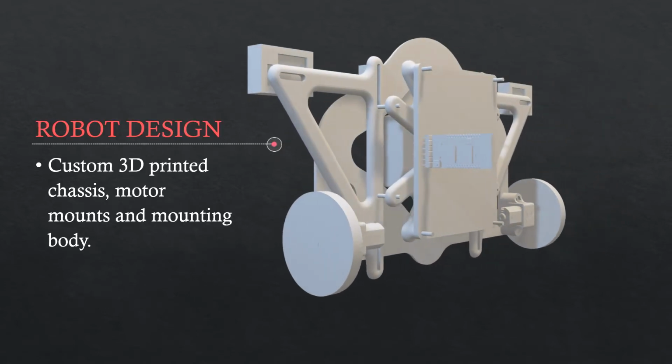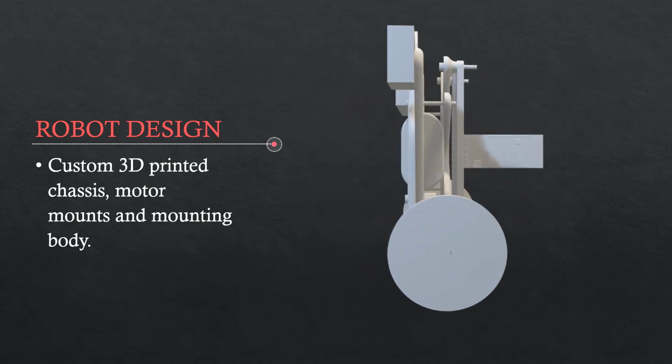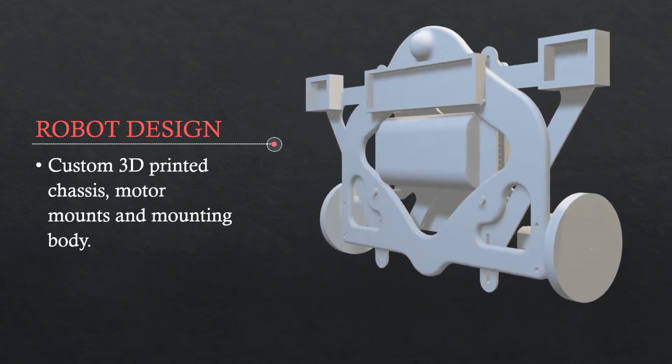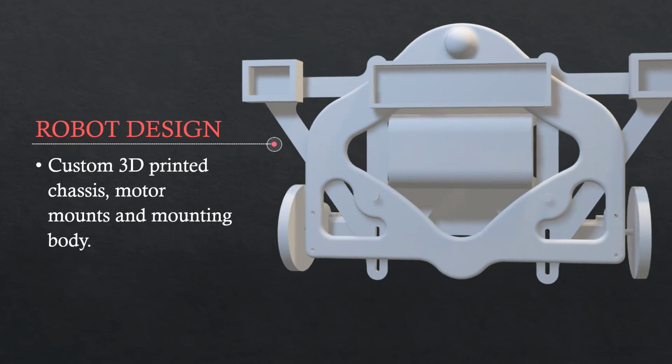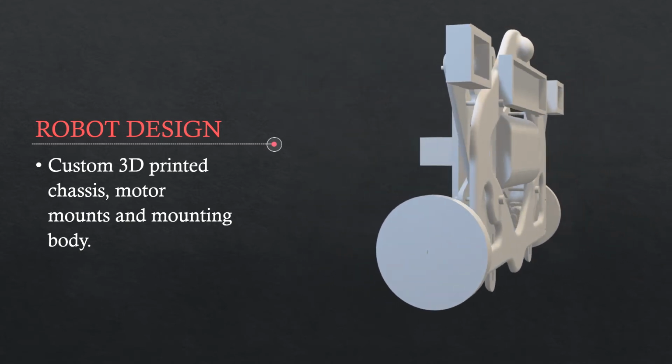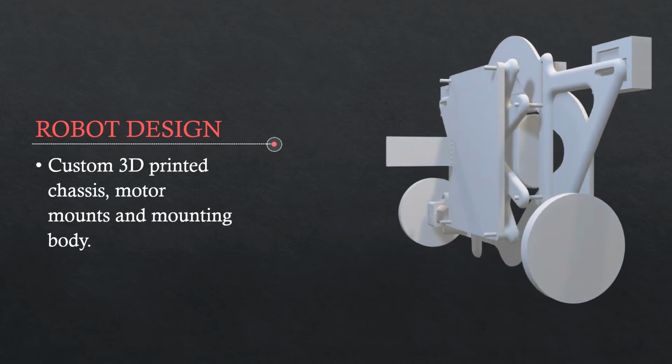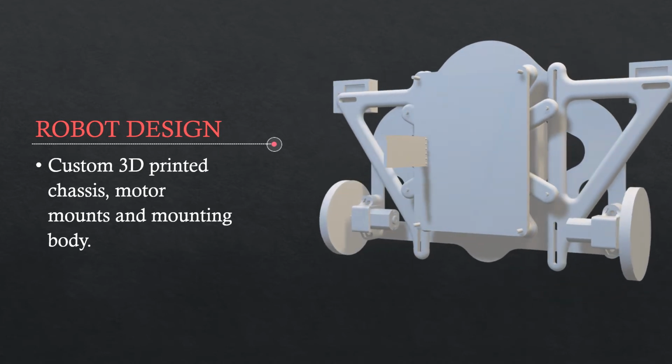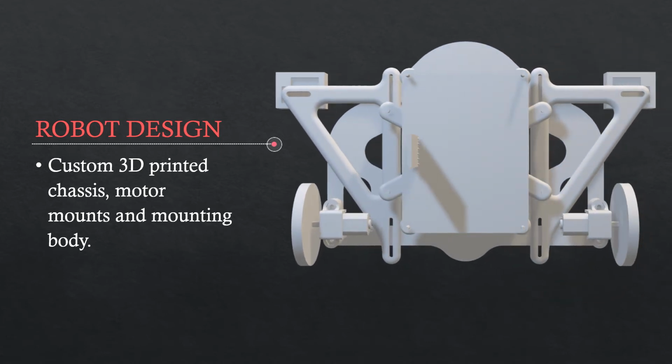The chassis is entirely comprised of custom designed 3D printed parts. This allows for a higher degree of adjustability and modularity. The final iteration of the design is dramatically shorter and has also received a thinner wheelbase than the first iterations. This allows for a tighter turning circle and for the robot to stay on track better.